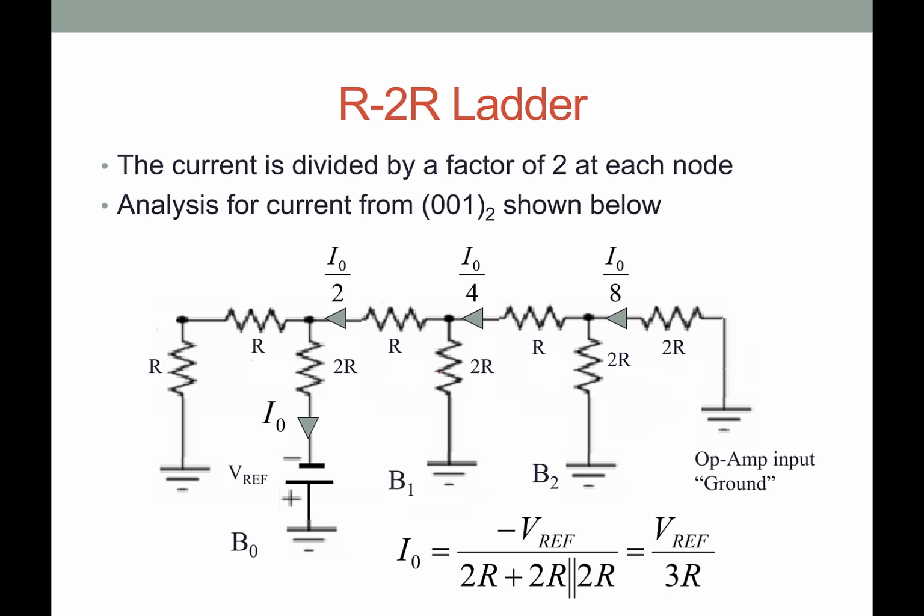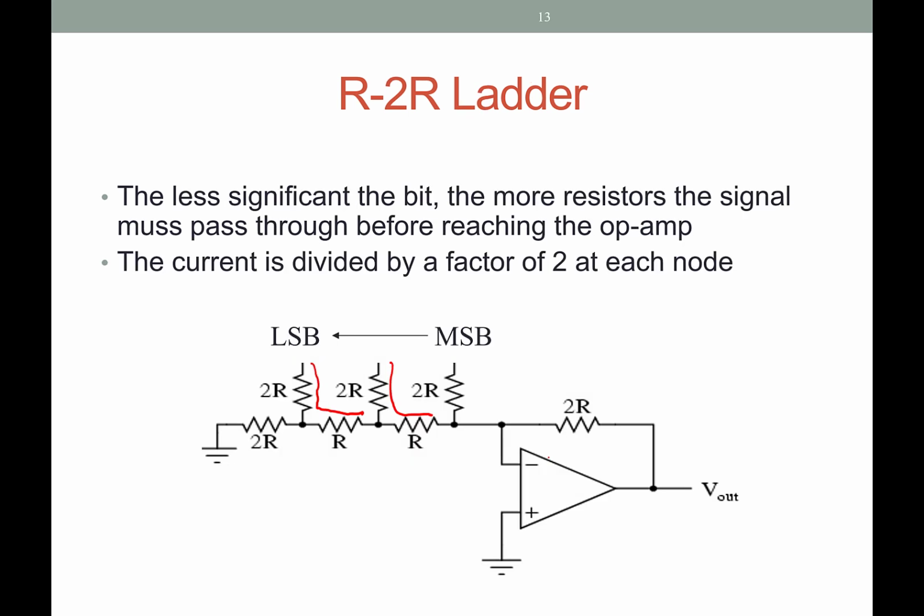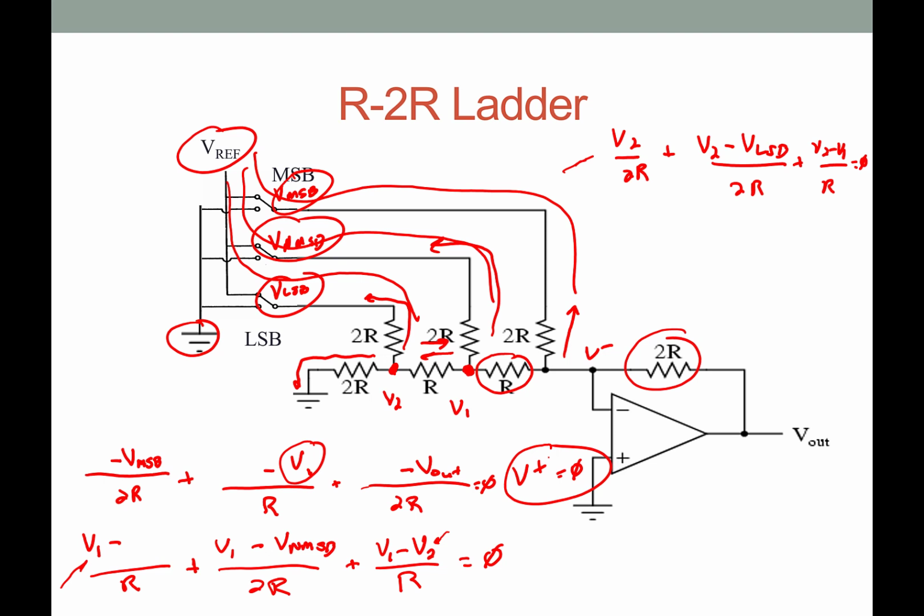And notice in this case it's showing you 0, 0, 1 being your input, and so the voltage Vref is set there at that lowest bit. These are both tied to ground, and so that's going back and looking at this one. That is putting Vref tied into this one, leaving those two tied to ground.